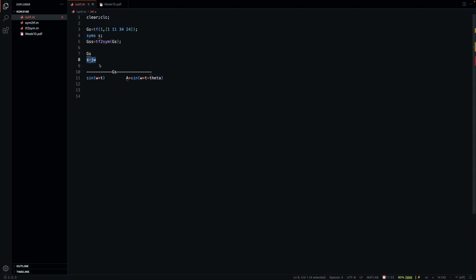We had this substitution before, but it's not the same, because before we talked about a characteristic polynomial, and if we have a root on the j omega axis, so s equals j omega, it should satisfy the characteristic polynomial. So this is not the same substitution. It may seem the same, but here the aim is to look for the roots of a characteristic polynomial, whereas here we substitute this into the transfer function itself.